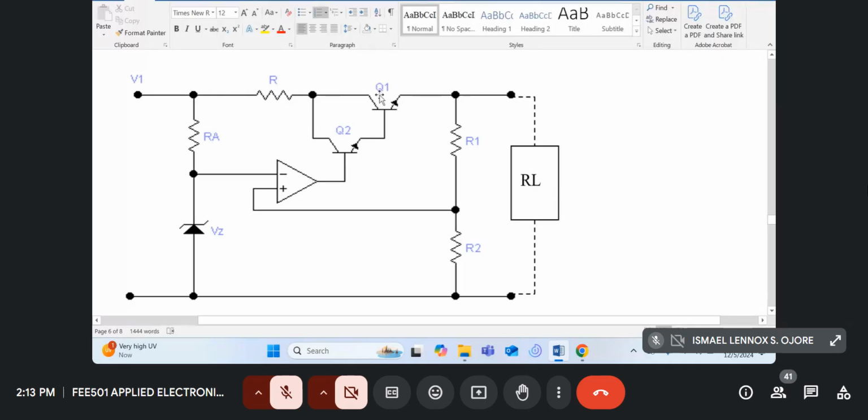So most of these output transistors are normally power transistors, which are connected to a heatsink, and their gains are normally quite low, maybe 20. So if you've got half an amp coming at the base, half an amp times 20 will be 10 amps.